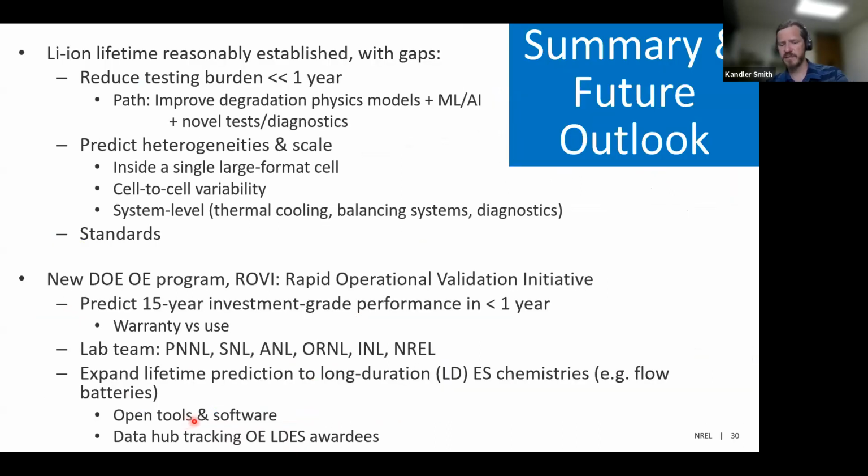Okay, and with that, just a few concluding words, and hopefully I'm not too late on time. So I would say lithium-ion lifetime is reasonably established, but there's definitely some gaps in our knowledge. Right now, it takes, I'd say, typically 9 months of test data on some 20 cells in order to get a pretty good lifetime prediction out to 15 years and have some idea how it's going to change with operating condition. So a pathway to make that faster is to connect the degradation physics into physics models, and build together those with machine learning and AI.